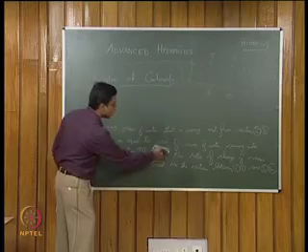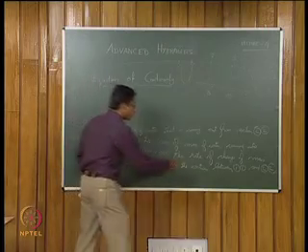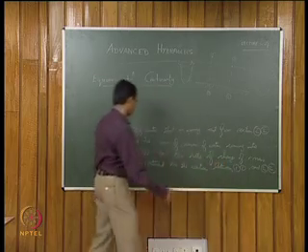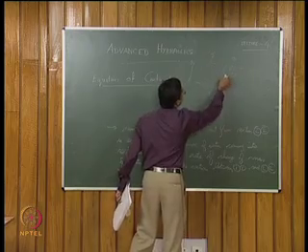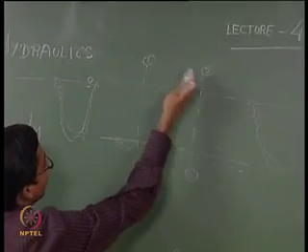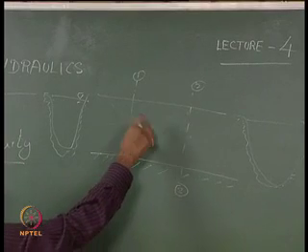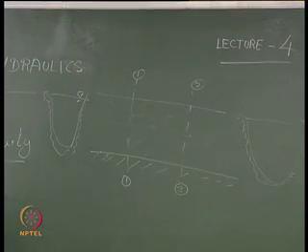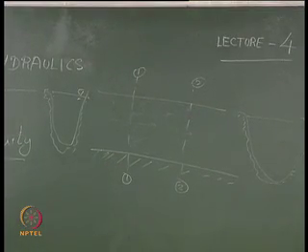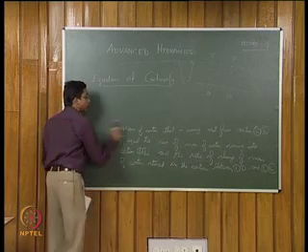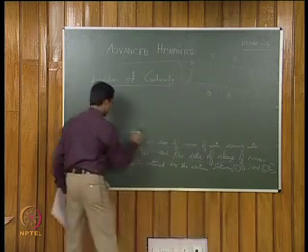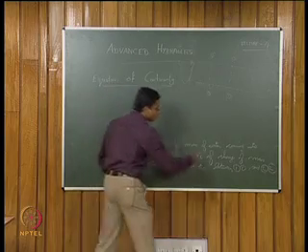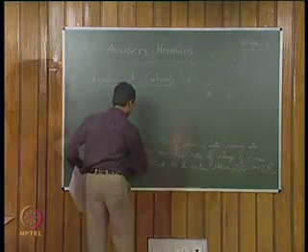As the definition suggests, there is a particular quantity called the rate of change of mass of water stored in the section. So, how much amount of water is stored here between sections 1 and 2 in the channel, and how much it is changing with respect to time, that is also a dependent quantity. Now, in a simple case wherever you are dealing with steady state conditions, this particular term vanishes off.